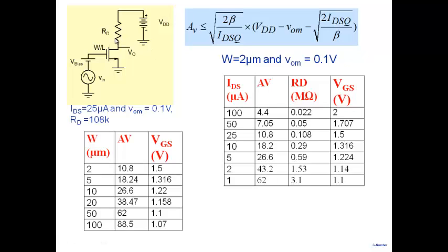We have seen that in bipolar also. How do you get large gain without requiring large supply voltage or large values of RD? Replace the resistor by a transistor, and the idea is that you get an active load. And what kind of a transistor will we use?